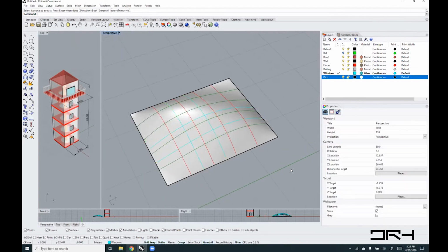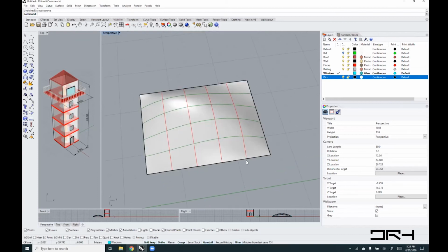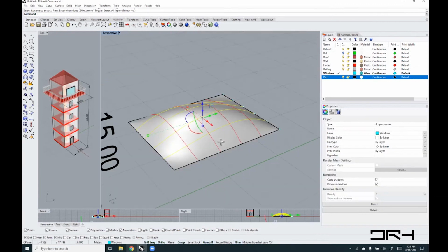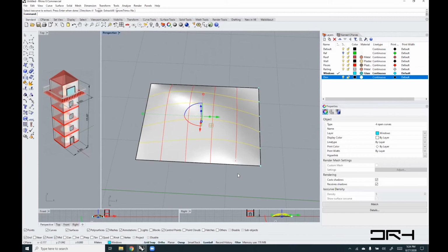Many times you want some reference points to extract, like equal intervals along your surface. So always do something like Divide, select the edge, and say I want to divide it into 5 segments. Then when you extract the ISO curves, you have something to snap to. I already know I want to go along the V because I want the green part. Then you can quickly snap to all the points to accurately extract the ones at the location you want. Any other questions?